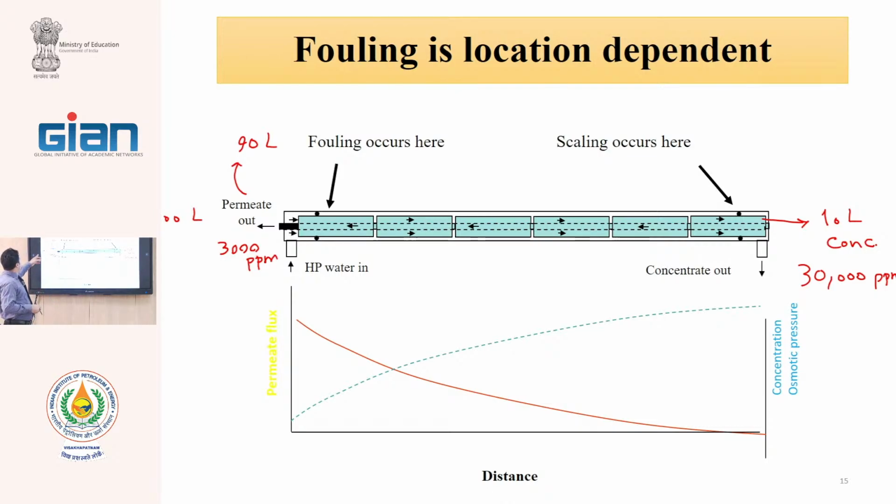The permeate is pure distilled water, no salt. All of the salts from 100 liters go to the concentrated solution. Therefore, concentration will be increased from 3,000 to 30,000. Therefore, here we have a high possibility of saturation. 10 times we have a thicker solution.